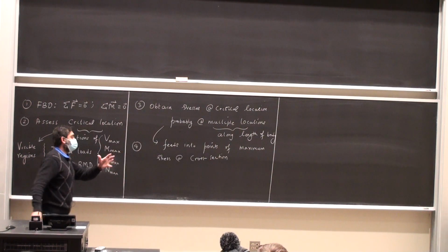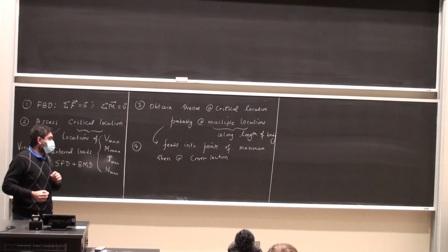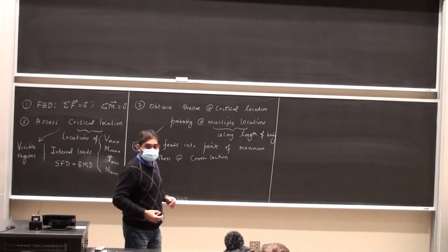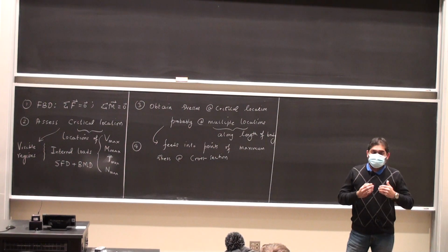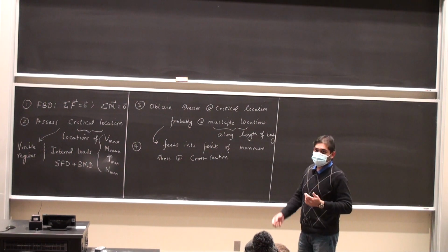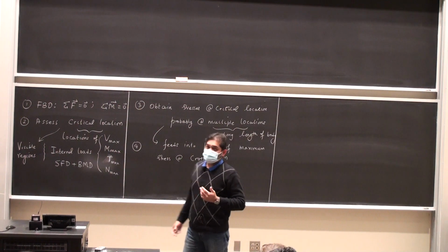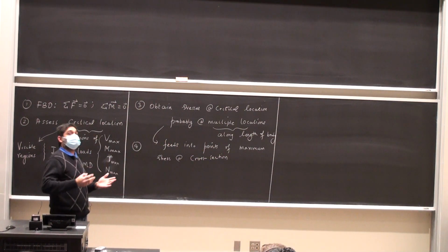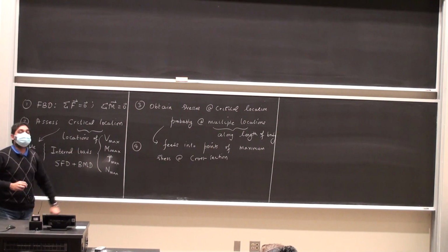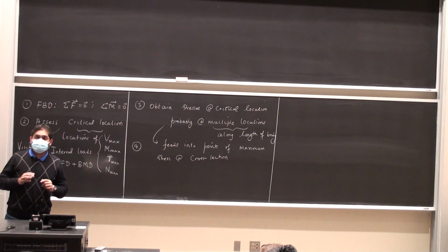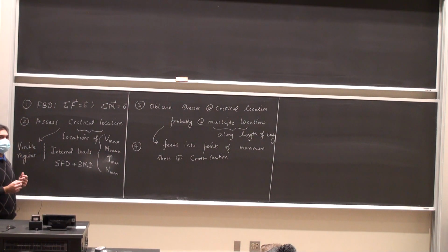Cross section, if you're doing a problem on torsion, any point on the outermost circumference is a point of maximum shear stress. If you're doing a problem on bending moments, the largest distance away from the neutral axis is the point where the bending stress is the maximum. If you're doing shear stresses, transverse shear stress, which is the VQ by IT formula, then the neutral axis is your culprit. So these are all the locations that you're interested in typically, right?